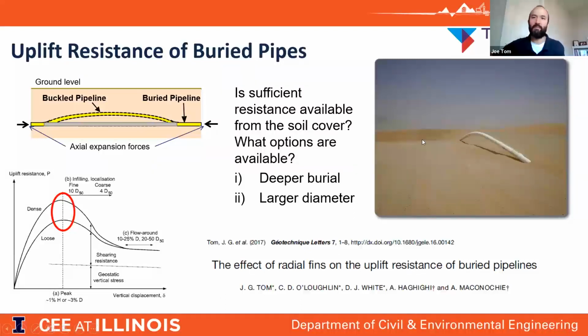I should say why they bury it is in general for protection. In places like the North Sea and on the east coast of the US, you have a lot of ships which have anchors, and you don't want the anchors to snag the pipeline if it's sitting on the seabed. And other things like fishing that use bottom trawling, you don't want that fishing gear to snag the pipeline. Even more interesting, in Newfoundland in Canada, they bury the pipeline to prevent icebergs from smashing into it. So there are lots of reasons why you might bury the pipeline.